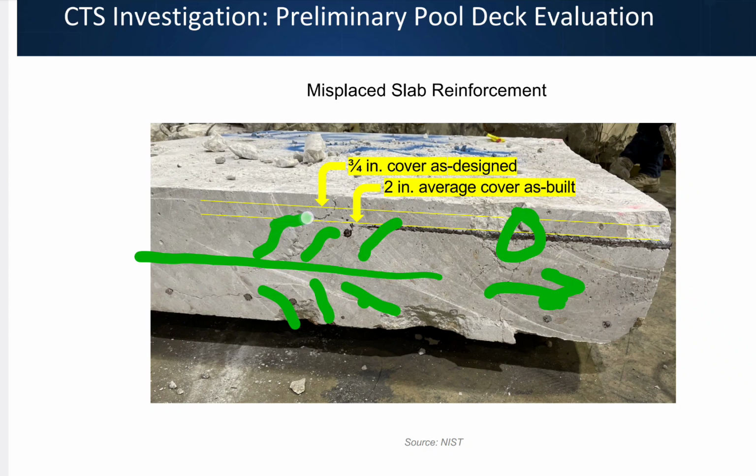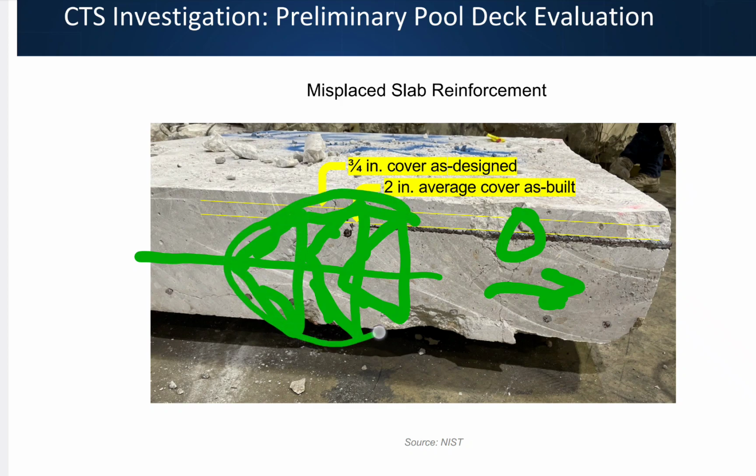And that creates this cone effect. These little cones, there they are. That creates these overlapping cones and stresses. Now this area here may act as one, and so it's a lot to try to pull out. If you just try to pull it out, think of the top side now, that this is the concrete.